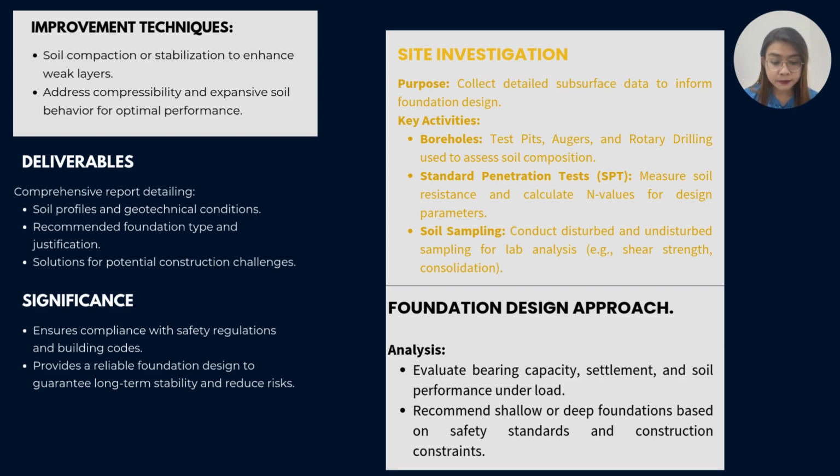Next is standard penetration test, which is SPT, to measure soil resistance and calculate N value for design parameter. And lastly is soil sampling, which is to conduct disturbed and undisturbed sampling for the analysis, for example, shear strength and consolidation. And lastly, foundation design approach.